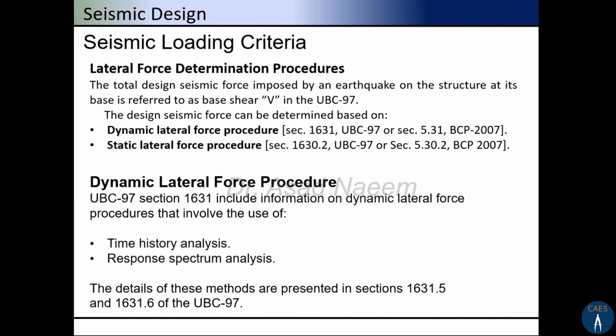is required for irregular structures, important building structures, or very important structures like nuclear power plants and main facilities like large hospitals. And we have to see that the seismic response can also be dominated by modes other than the fundamental mode. These procedures are more tedious and difficult to perform, so they are used for irregular buildings and other very important types of buildings.